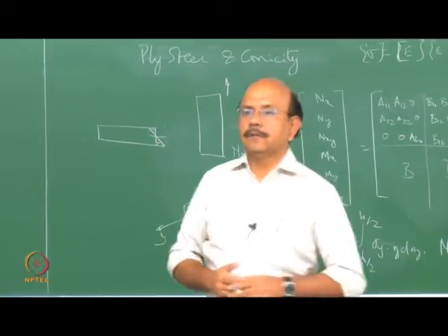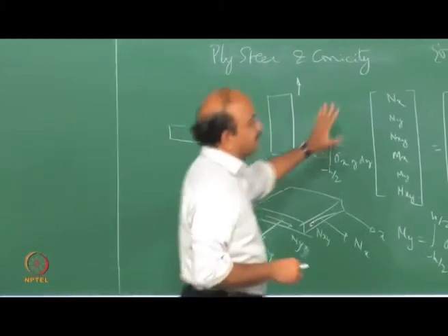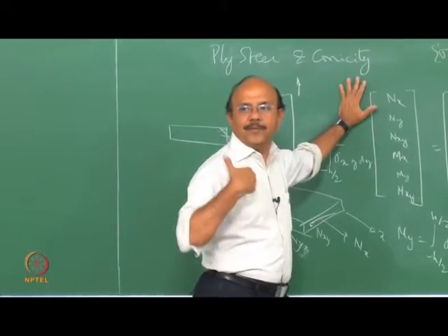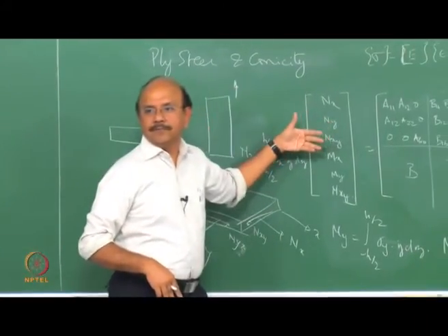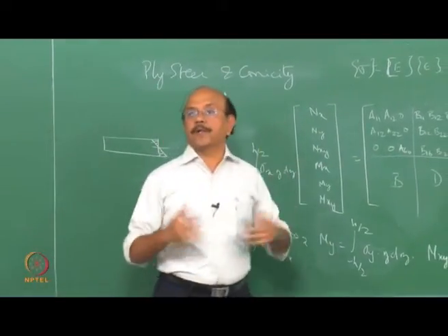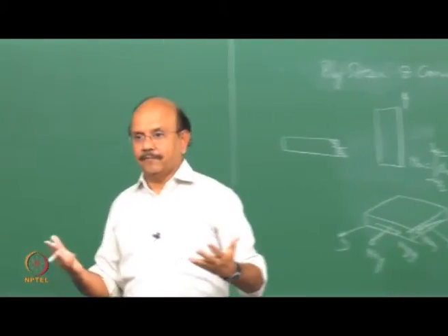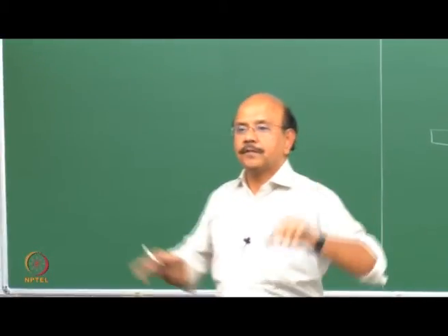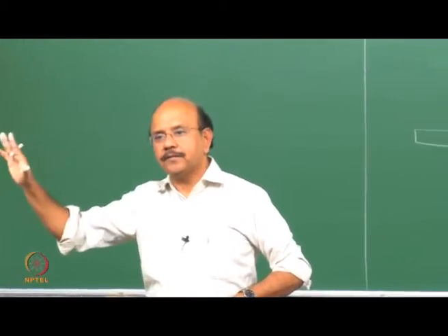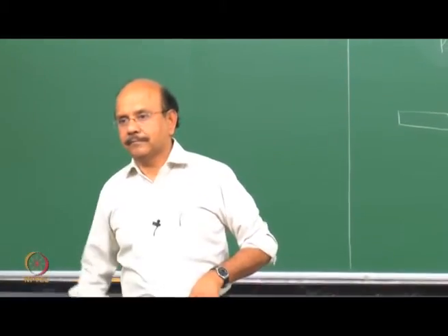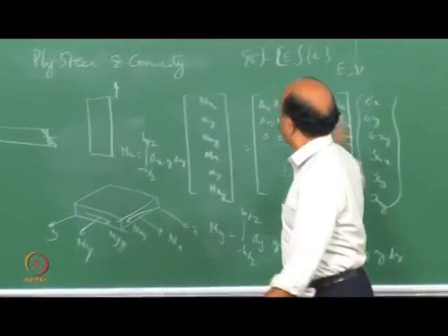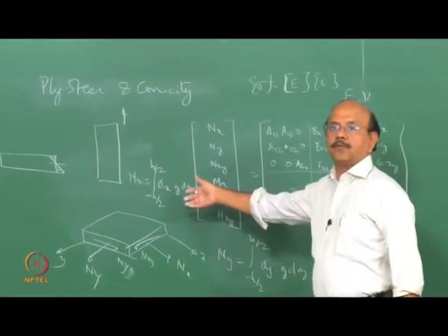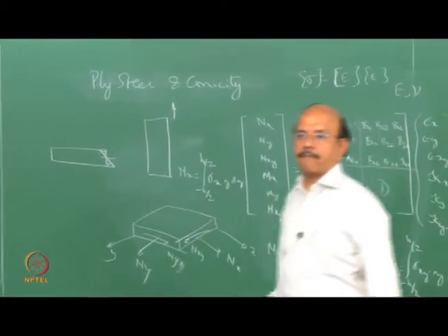Any questions? Notation changed from sigma to N over. Yes. This is right. This is the way you express it. I didn't say it's the same. I said it's similar. Okay. So this is the way you express it for a laminated plate. Okay, so express it in terms of force, express it in terms of strains, as well as curvature. Right? Okay, and those forces are of course related to the stress through those kinds of relationships.